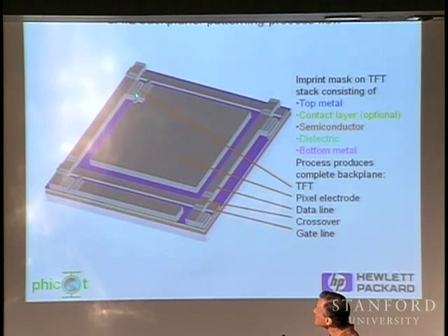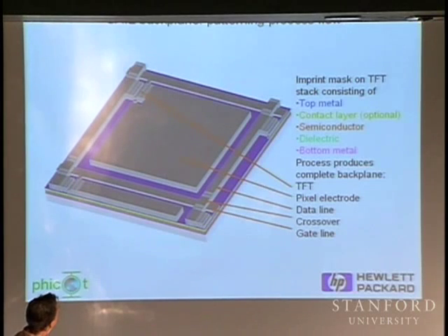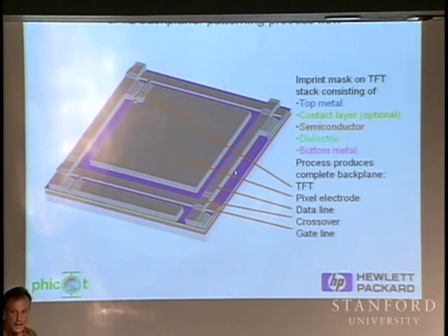The third height in our structure is the transistor channel height, and the highest molded part of the structure is what we're going to use to form our data lines. So each of these is a discrete height, and they're all separated by uniform step heights, in our case about 0.7 of a micron apart.